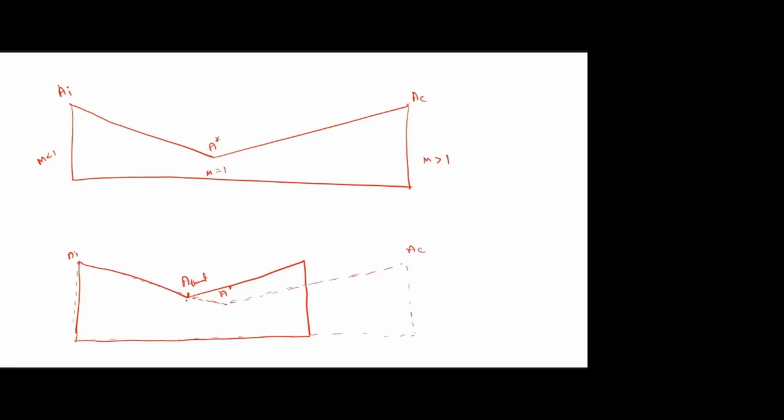So we cannot say this is A star, because the Mach number will not achieve sonic here. Maybe Mach number is 0.2, then 0.3, maybe 0.5, 0.7, 0.8. Here only it is achieving 1. But I have taken the wrong duct, so that in the throat I am getting some subsonic Mach number only. In that case, I should not mention this as A star. It will be AT or A throat. Is it clear? Difference between these two ducts.